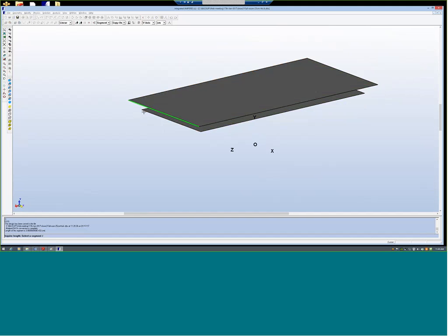This side will be slightly less than 3 meters. Actually, it will become 298 centimeters, because 1 centimeter on either side, if you cut it, this becomes 298. This is 600 centimeters, that is 6 meters. This is 598 centimeters it would become if the thickness is 1 centimeter.